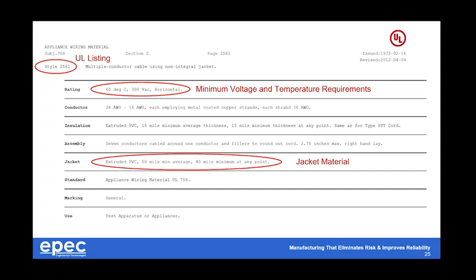And the listing here demonstrates that to comply with UL 2561, you need to survive the 60°C temperature requirement, a 300 volt AC dielectric breakdown, and then a horizontal flame test. This also requires that the center conductor ranges from 16 gauge to 26 gauge.